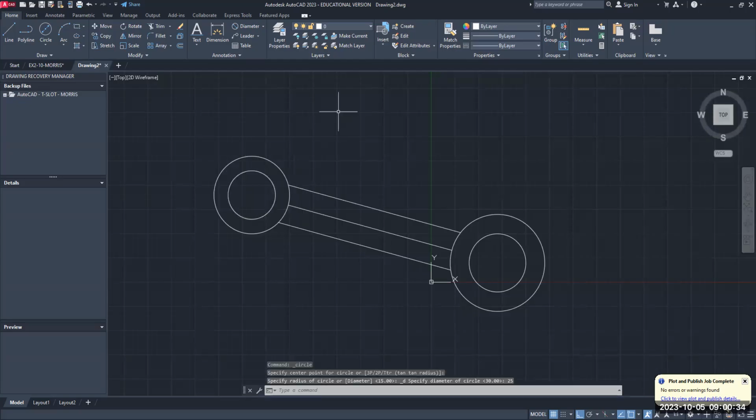All right, now I'm gonna go to where we had rectangle before, select polygon, but you gotta be careful of saying only 4 sides. See down here at the very bottom, it says your polygon is only 4 sides. I want it to be 6. I don't know why this won't let me change it. So one more time, go to this one here, select polygon, type in 6, enter, specify the center, click.